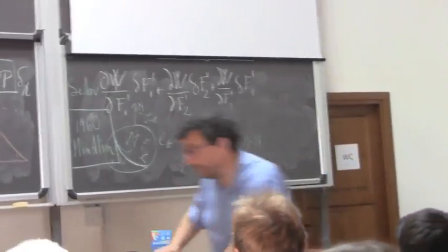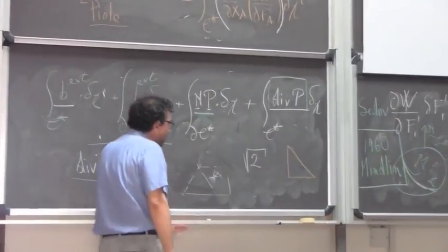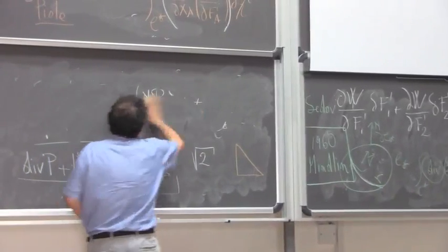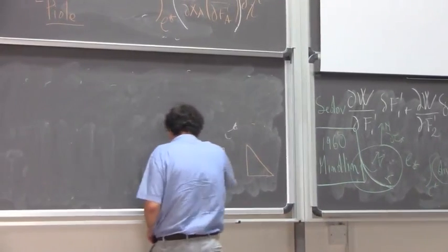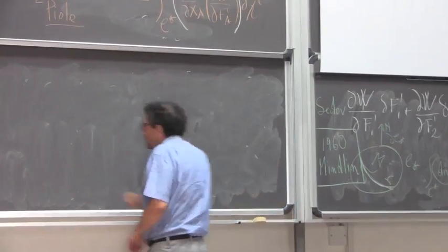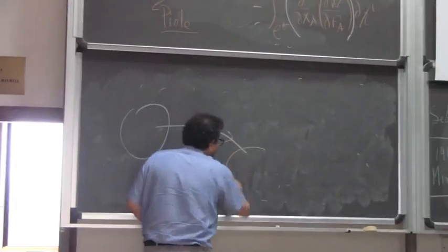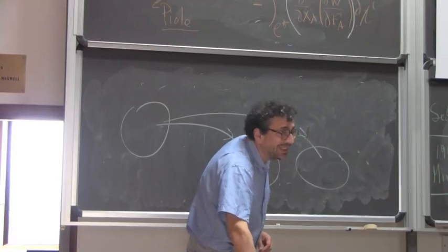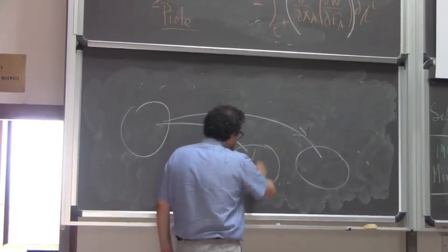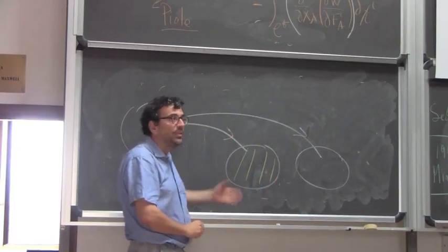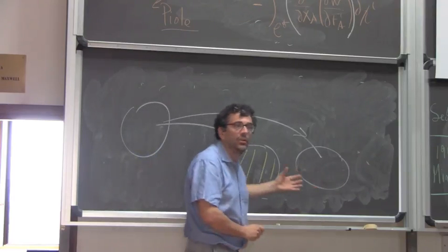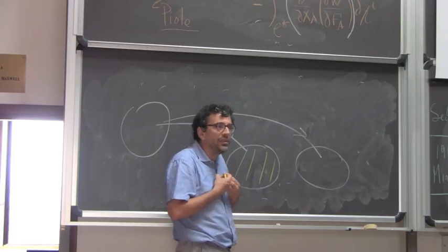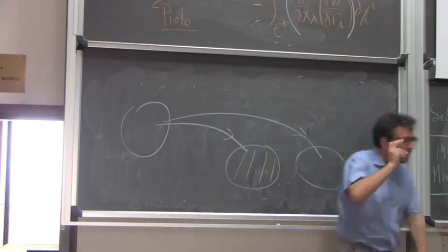Lagrange integration. Okay? I want to explain this to you because it is very useful for applications. If you have a fluid or a solid occupying different positions at different instants, you can decide to write your equations in the actual configuration. Which is the problem? The actual configuration changes. So the domain of your fields is unknown.